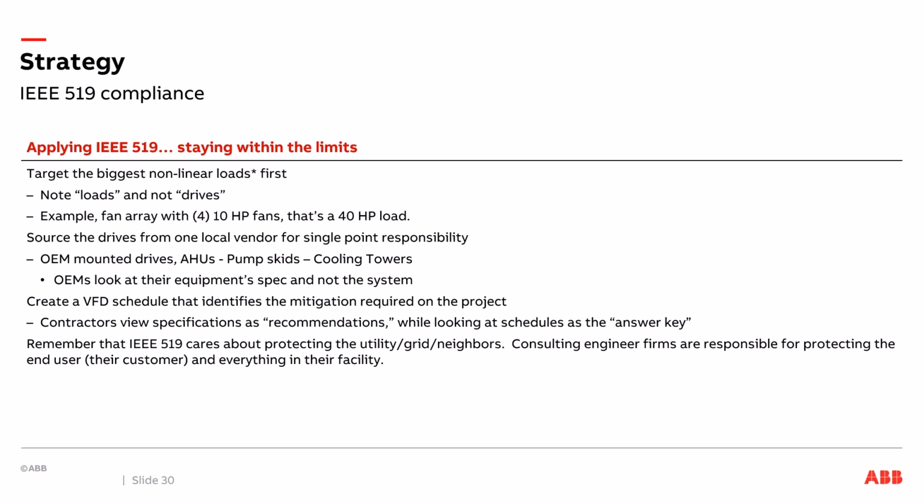Also, as much as I love IEEE 519, remember that it's about protecting the utility, the grid, the neighbors. You as the consulting engineer, if that's your role, are responsible for your customer also. So you need to still consider voltage distortion. Don't just get hung up on the current distortion.